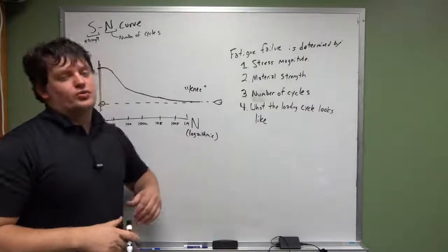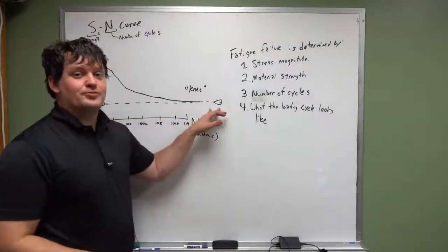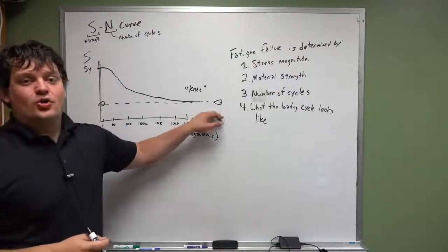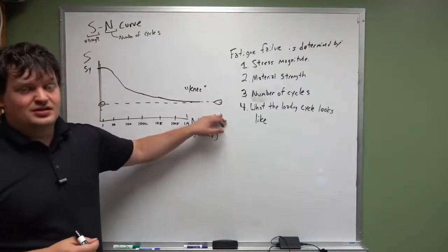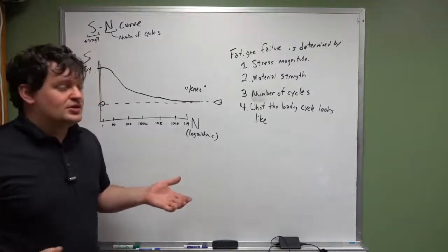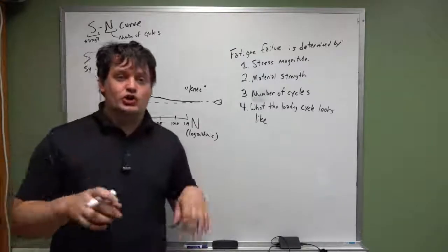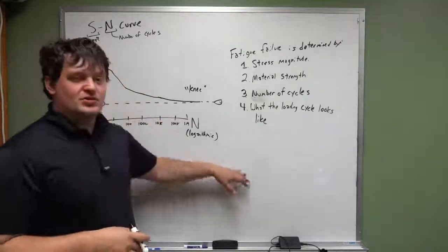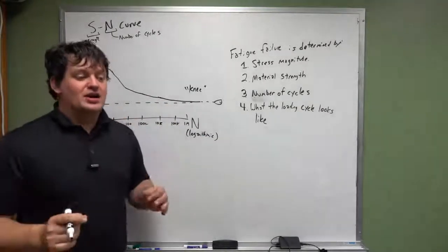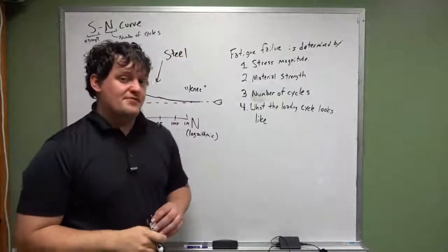When car manufacturers create axles, they determine this value by cyclically loading an axle repeatedly. And once they've found what that strength value is, then they can use it for all of their axles. And that's all it takes. They know where this plateau happens. They know where this knee occurs, where you have an infinite number of cycles that a material can handle at this load. Okay? Now, I'm going to go ahead and say this is for steel. This is not for aluminum.